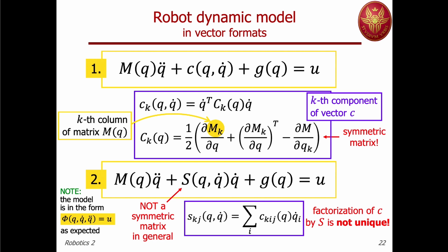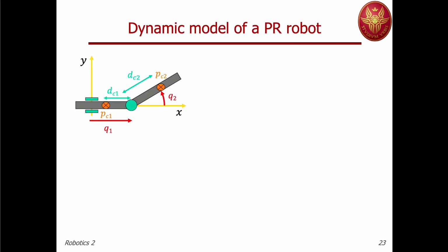No matter how many joints there are, no matter how the links are made, heavy, light, uniform mass, strange couplings, prismatic joints, revolute joints, all the robot models will have this structural form, which we derived in symbolic terms using the Euler-Lagrange approach, which is an energy-based method. And this is the advantage of this situation.